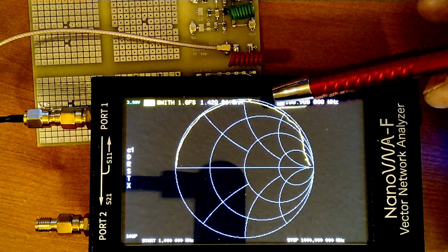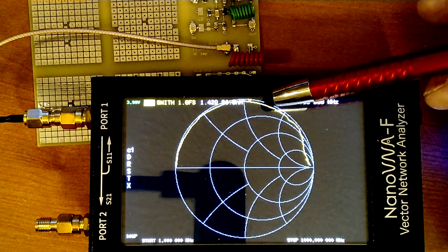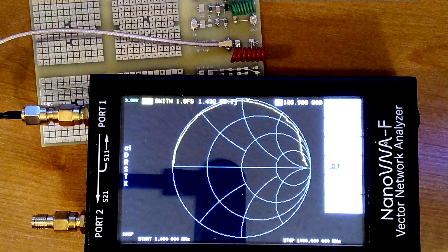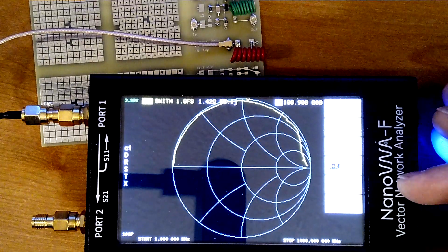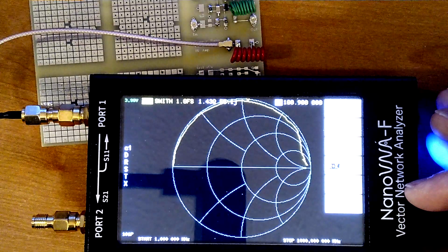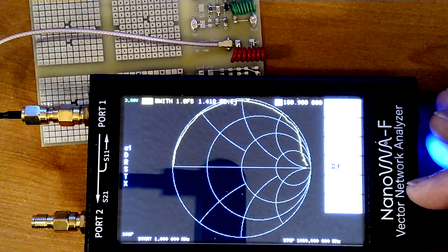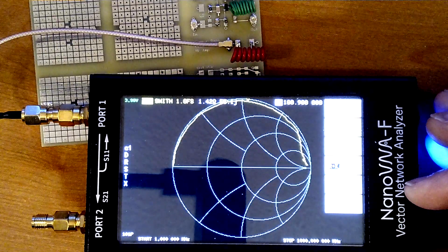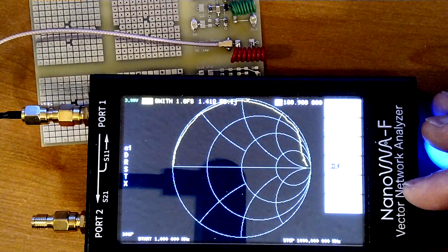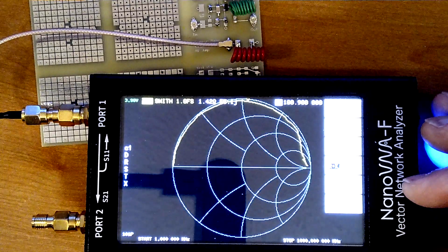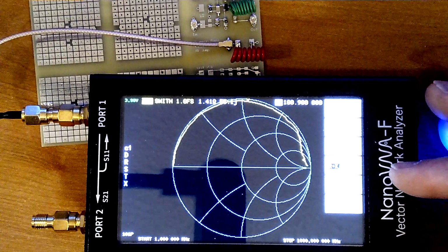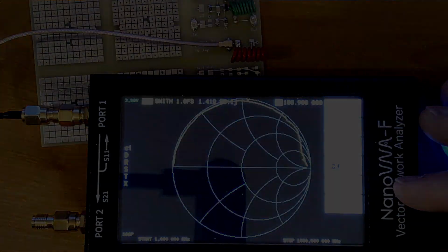Now, the other thing that's really cool about the network analyzer is you can measure what's called the quality factor of the inductor. And this NanoVNA gives you that ability. I've used network analyzers in the labs that cost $40,000, and this thing, frankly, performs for all of the applications I've been showing here just as well as those do. There are some limitations. In particular, this only goes up to a gigahertz, but if you're working in that frequency range, these things are stunning.